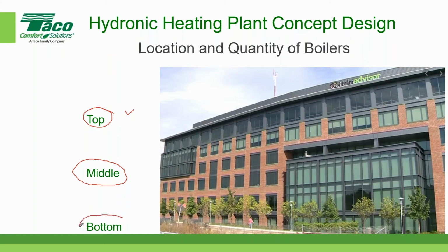And the other option is to put it at the bottom. So in this case, one of the advantages of putting it at the bottom of the building, since this is a heating plant, and you'll see in a moment I've chosen some temperatures, is that there'll be a certain amount of hydronic static pressure available if your heating plant is at the bottom. So you'd have less concern about pumps cavitating, because you want the available net positive suction head to be greater than what the pump requires.